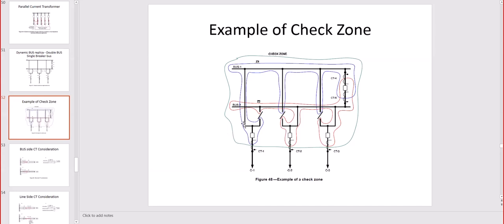So we got a zone that is the blue zone for after the transfer to the transfer breaker, right? So now we need to incorporate the transfer breaker as opposed to the normal breaker only, because we have closed that breaker. So transfer breaker need to go in zone 1 and also in zone 2, because we operate that to transfer loads from bus 1 to 2, so during transfer.